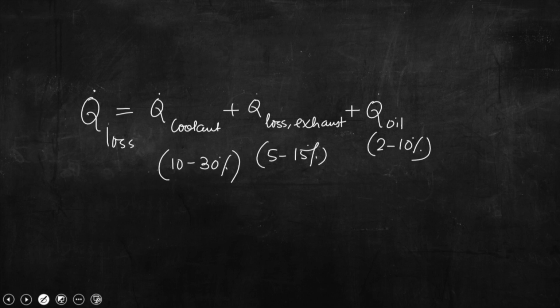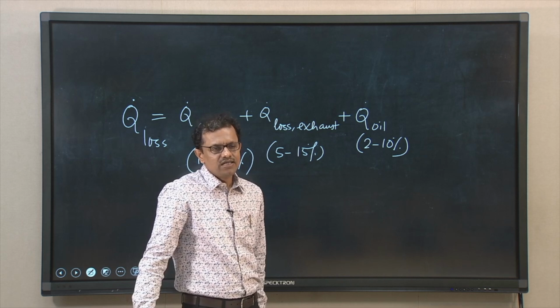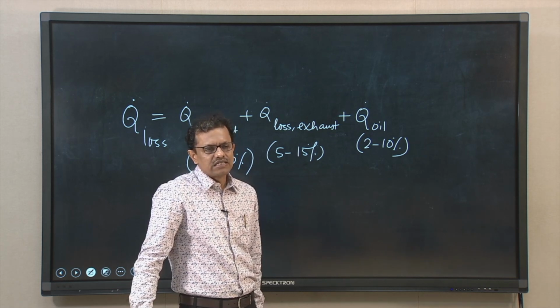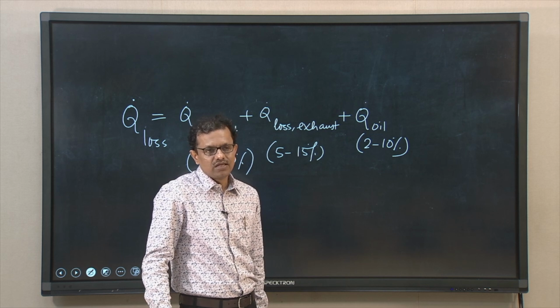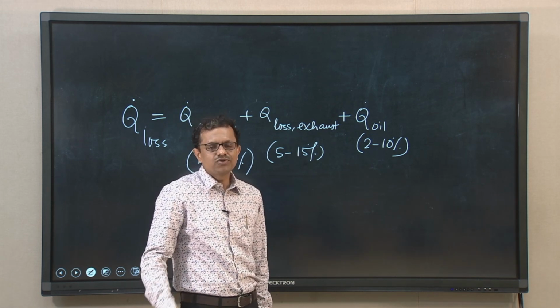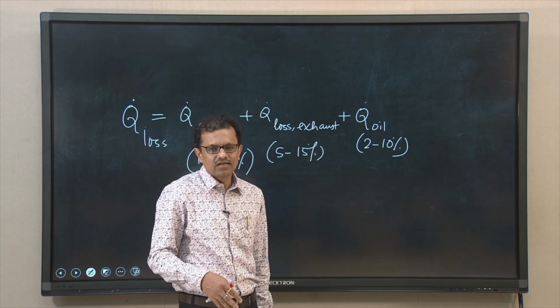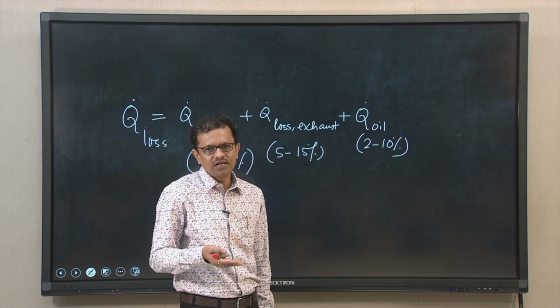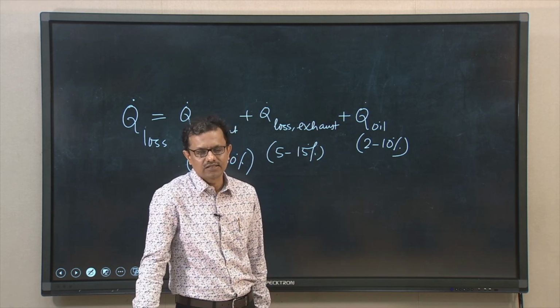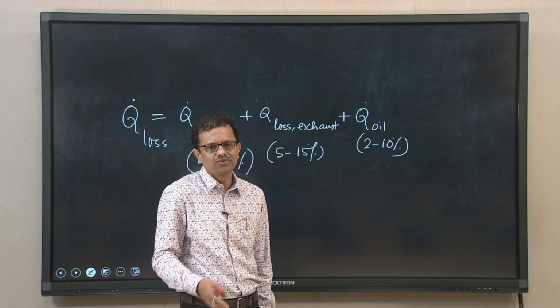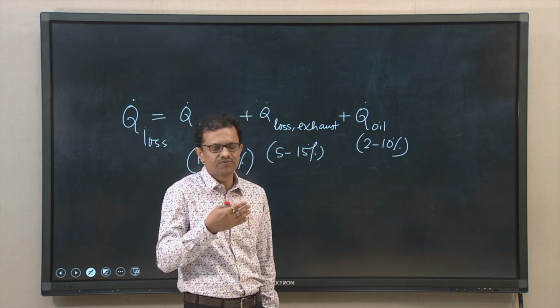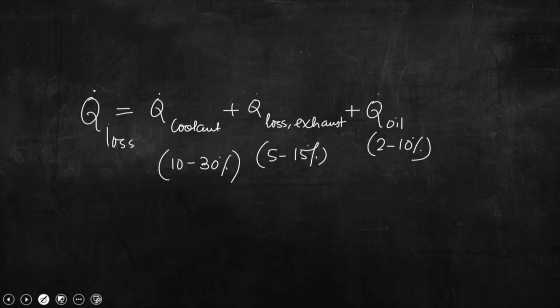We have discussed that transfer of energy by oil, that is lubricating oil, is there because there are a few spots in the engine block where integration of a cooling system is not so easy, like the piston face. The piston face is exposed to the maximum temperature of the engine cycle, which develops during the combustion process. So lubricant is splashed over the piston face, which in turn removes a certain amount of heat from it. We discussed this part in the previous class.